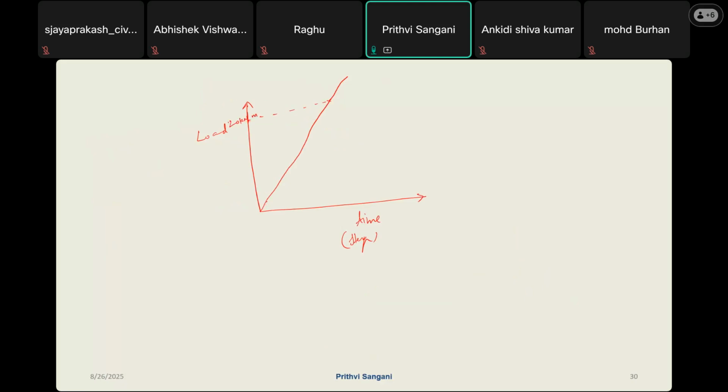So for each step, slowly it is trying to increase step by step up to this part. And when it is the 15th step, it came up to 20 kilonewton. Let us say if you want to see what your results are for 10 kilonewton per meter load, you can simply query this step, which in our case is maybe the 8th step. Or if you want to know the result at a very small load of, let's say, 2 kilonewton per meter, then it will be your step 2 or something.